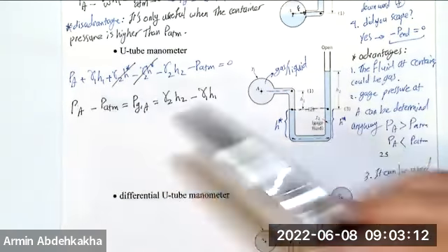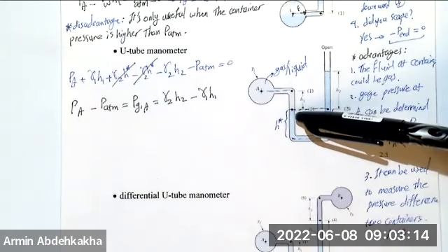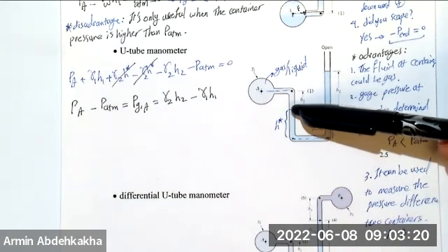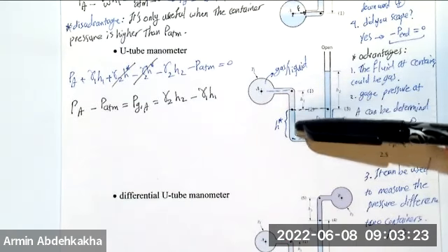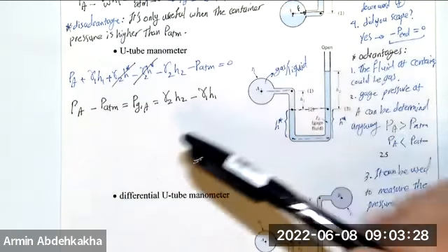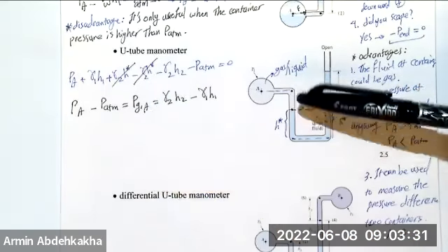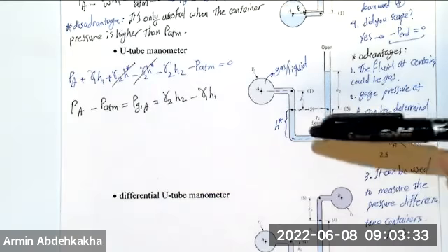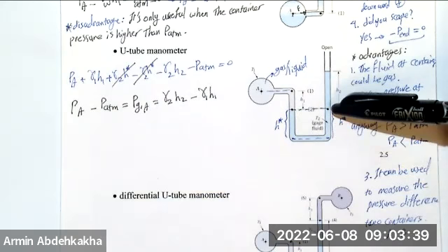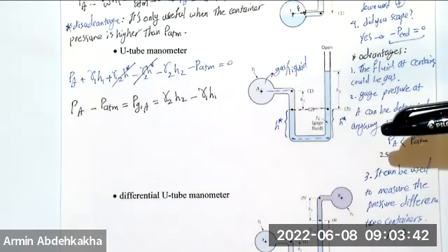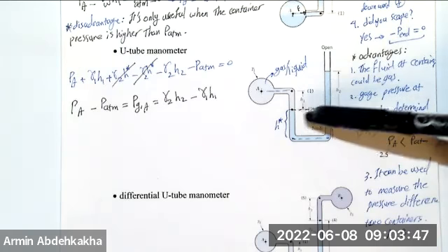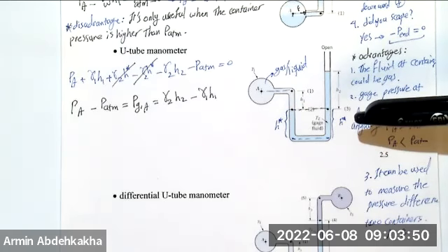So still PA. Then coming down to this line, why? Because here the fluid is going to change. This one is the gas and this one is the liquid. Coming here, stop here and write minus gamma or plus gamma 1 h because you are coming down, right? But from here, they are not coming down here and here. They're jumping from here to this point 3. That's why we have points 1, 2, and 3. They're jumping to point 3 because they're on the same line, right?